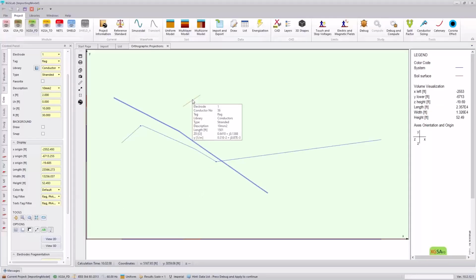I do have a couple things I want to do. One of them is that this pipeline is parallel-ish to our transmission line for a little over 1 mile, so 6,000 feet. So I have some concerns that this length of this pipeline is not sufficient to fully model my system, meaning that if I run this model right now, I could have end effects because this pipeline is a coated material and can hold that voltage for a much farther length than what I have modeled here.